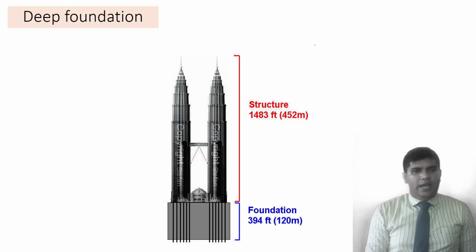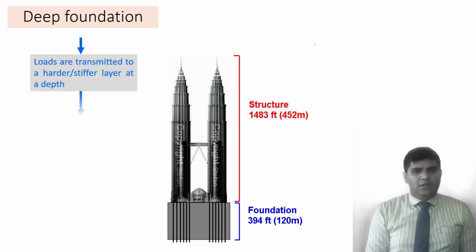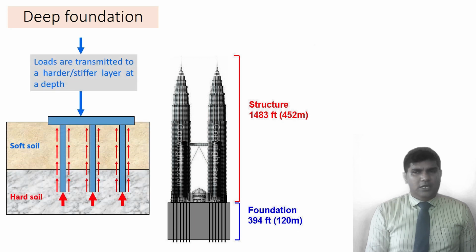And if you move to the deep foundation, where shallow foundations are not adequate to transfer the load, then we have to go with the deep foundation type. I told you that high-rise buildings commonly use pile foundations or deep foundations, because no type of shallow foundation could bear the load, and the soil could not support the building pressure.